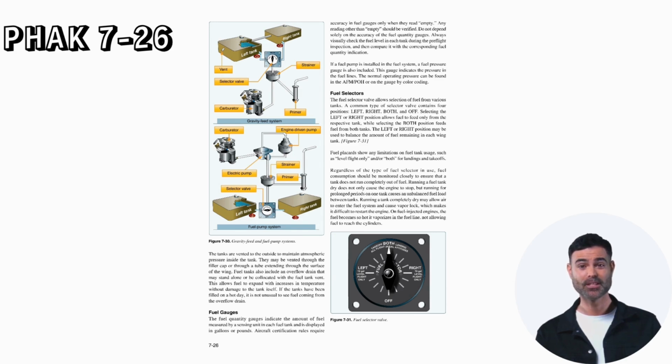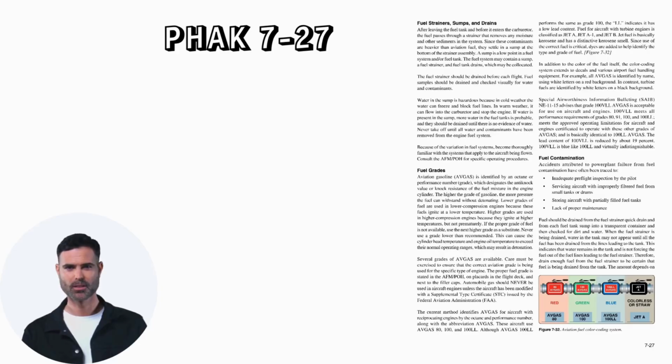Running a tank completely dry may allow air to enter the fuel system and cause vapor lock, which makes it difficult to restart the engine. On fuel-injected engines, the fuel becomes so hot it vaporizes in the fuel line, not allowing fuel to reach the cylinders. Fuel strainers, sumps, and drains.